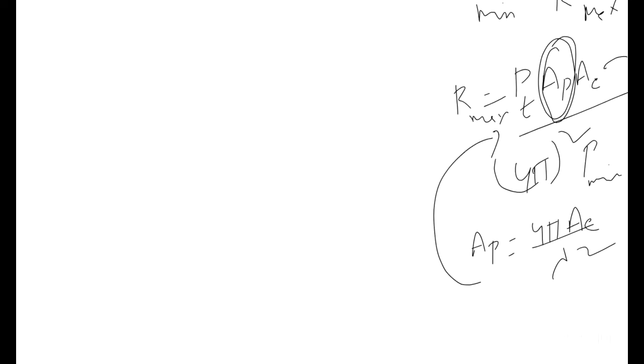Here the duplexer has two gas discharge devices. What are the two discharge devices? One is the transmit-receive (TR) device, and another is the anti-transmit-receive (ATR) device. These two act as a switch. What is the function of each? TR protects the receiver. ATR protects the transmitter.